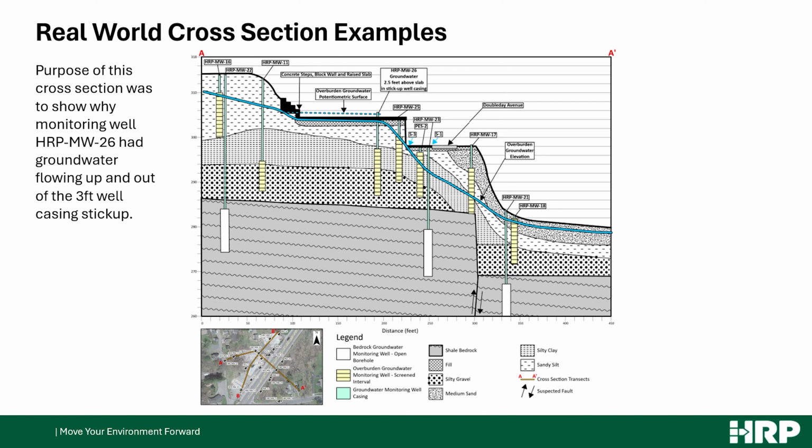We also mapped the geologic features for the region. And we noticed that there was a fault that ran basically along this stretch of road. And it continues all the way through Saratoga, all the way to the north. It's part of the geologic feature that's responsible for the hot springs. And we noticed an offset of approximately 15 feet when we drilled several bedrock wells. And this bedrock offset corresponded with a rapid change in topography.